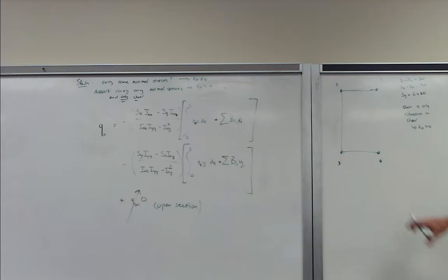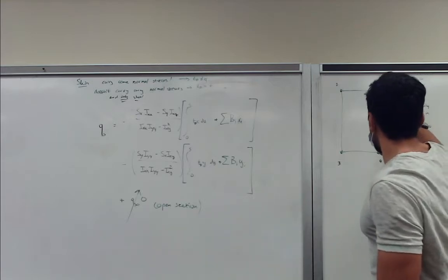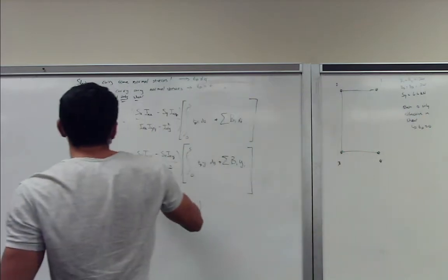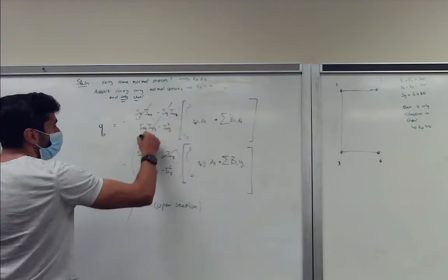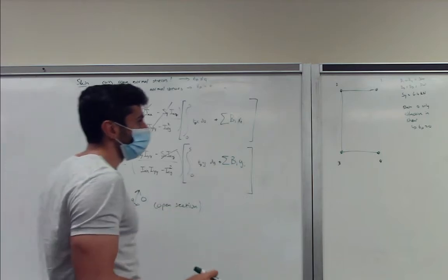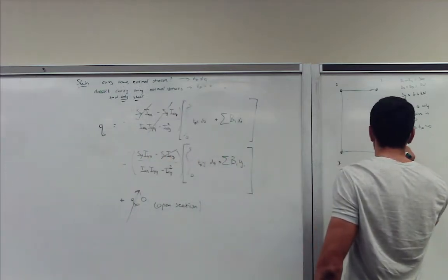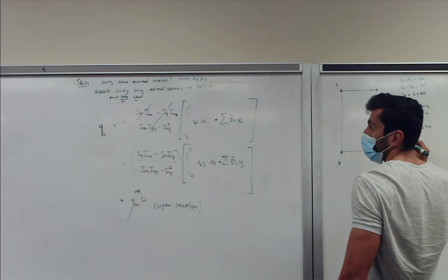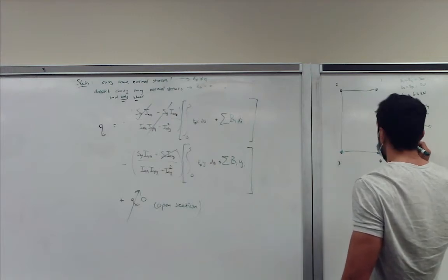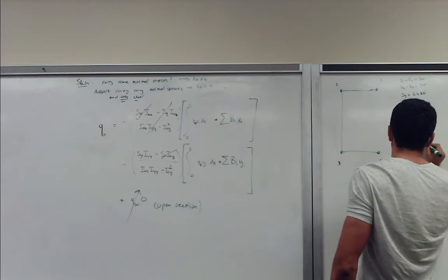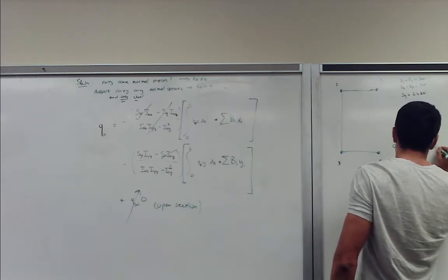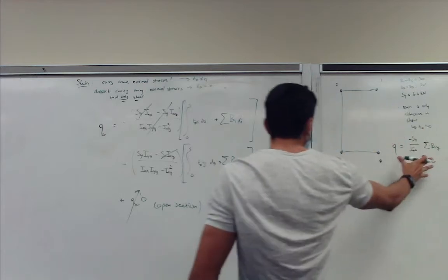Then we can repeat this and reduce that equation. We have only an Sy given, so Sx is equal to 0. It's symmetric, so this drops, and this reduces to q is equal to minus Sy over Ixx, in this equation format.